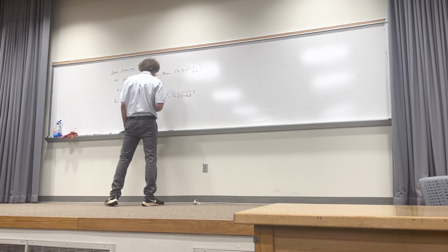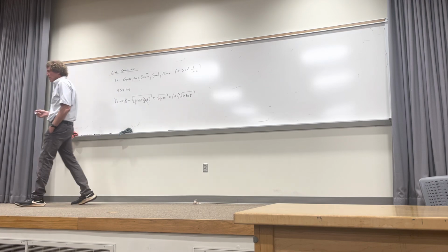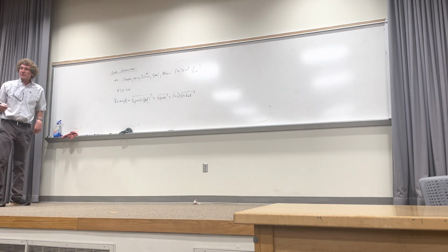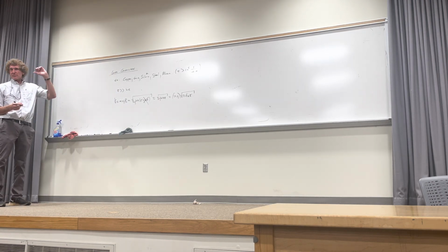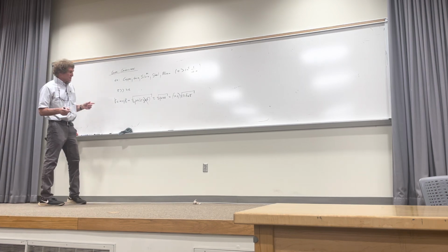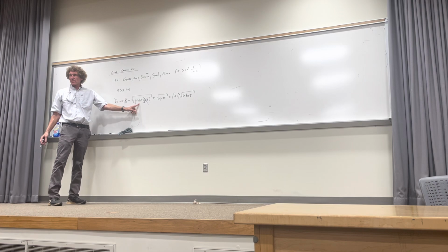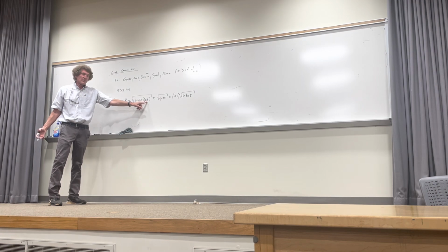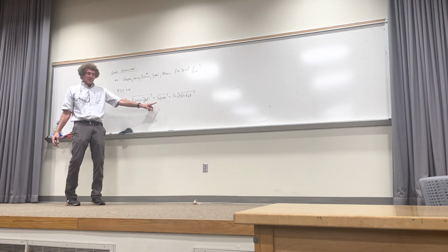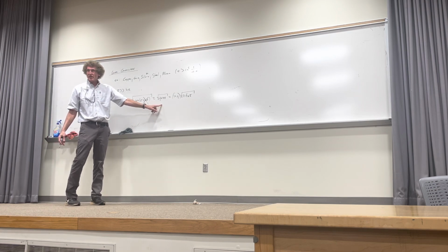Now I'm going to stop for a second and let you take a look at what I wrote. I went through this a few times. How many remember me going through this? Okay. Then I'm making a few points. First, that's the general form for the propagation constant, for gamma. When you have a good conductor, sigma is so much greater than omega epsilon, you can ignore the j omega epsilon. So that means you end up with this, right? Can you all see this okay?